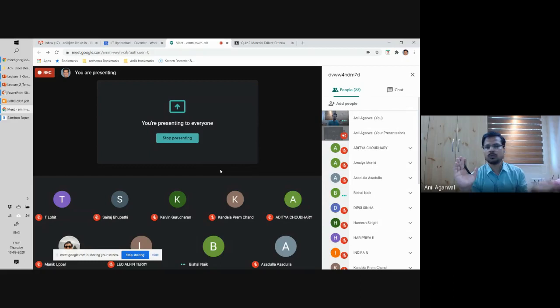if you say that the dead load of this building is, let's say, 2000 ton, how do you get at the 2000? You take the measurements, you know the member sizes, the slab thickness, the amount of steel you have used. From there, you calculate. And when you actually measure the weight of the building, you will find that you will be off by maybe 5%, most likely. You will not be off by much. For such things, you can have a very steep, very narrow kind of distribution, because if you have 100 such buildings, you will always get values in that range only, very close to your original estimate.